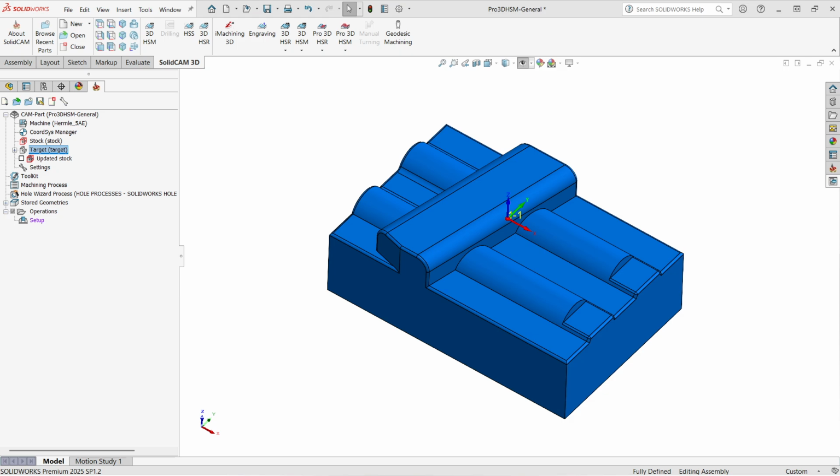After a finishing operation with a larger tool, some areas, like corners or fine fillet areas or some steep regions, may remain unmachined in the complex core cavity. Instead of remachining the whole part, rest finishing detects and machines only those untouched areas. SolidCAM does this by sweeping the previous tool diameter across the entire part and identifying the unreachable areas for creating the toolpath.